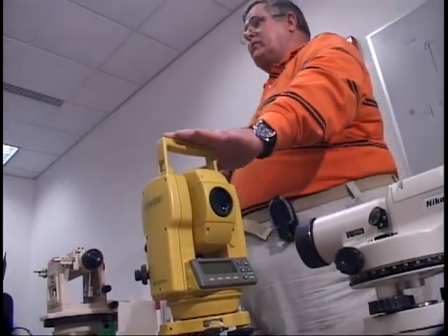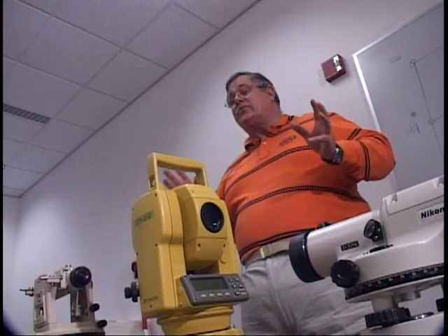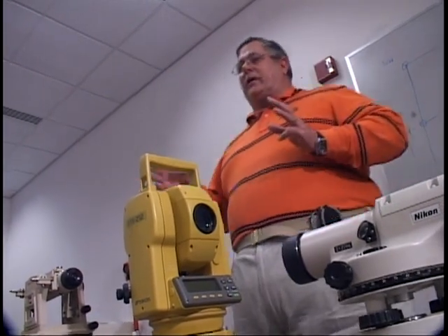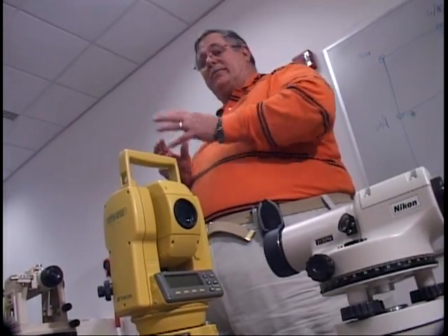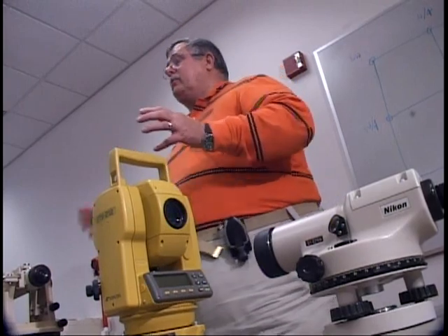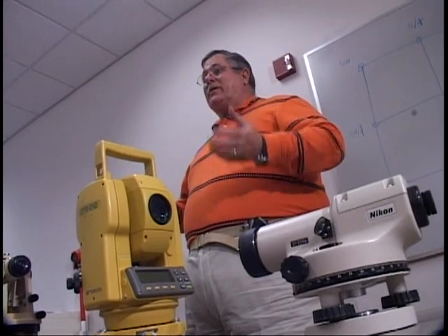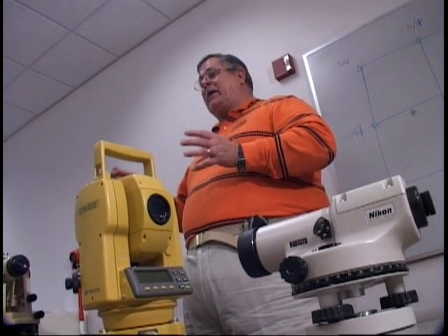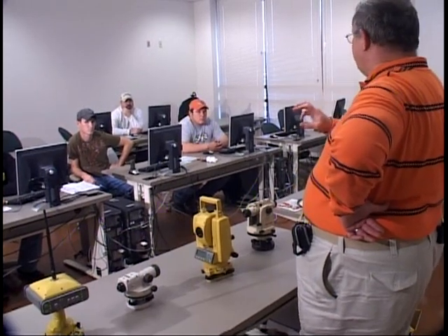With this particular instrument, you don't have to do that when you're using the data collector. Now, initially in this course, we're not going to be using a data collector. We're going to be using a surveyor's field book, but after we've learned how to do that, then we'll use the data collector. A data collector is essentially an on-board computer that records X, Y, and Z coordinates of all the measurements that you take, and the operator, all that information has dramatically reduced the time to take the information from the field and put it into a drawing form.